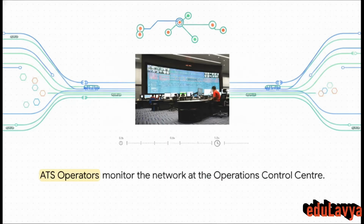If you step into an operations control center, you'll see human operators using massive ATS displays to monitor the entire network. Through the ATS, these operators can adjust dwell times at stations down to the exact second. For example, they can hold a train slightly longer at a platform just to ensure it merges seamlessly into a busy corridor without causing cascading delays down the line.